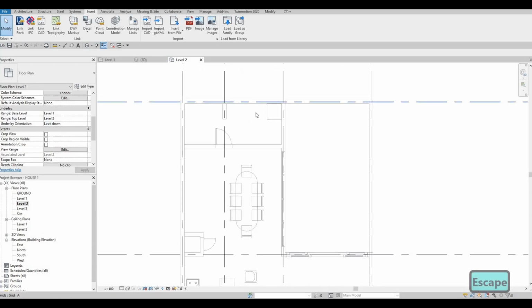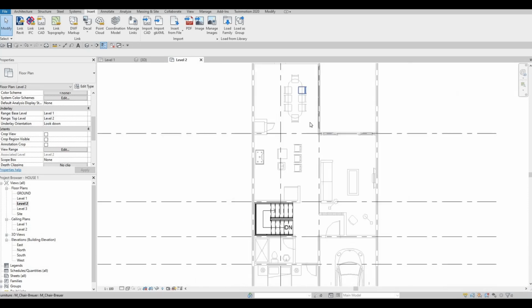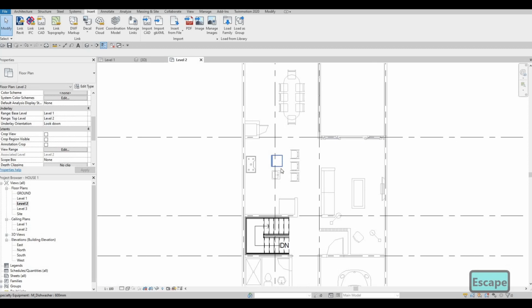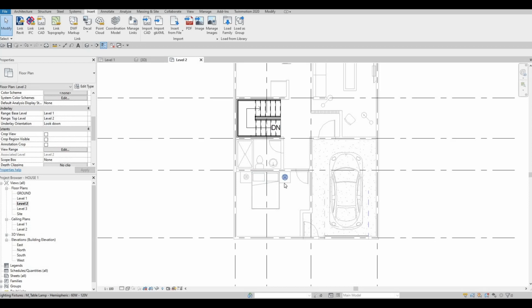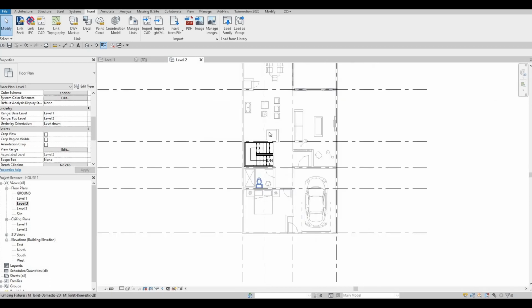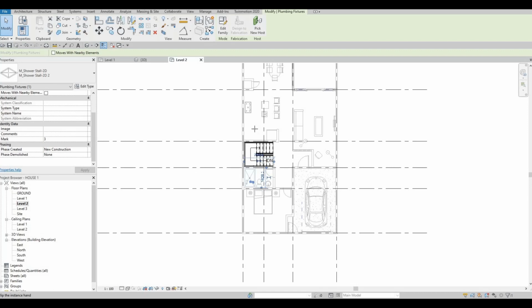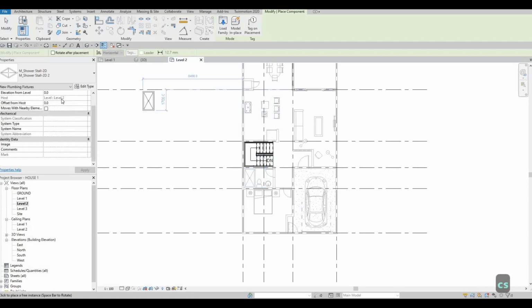And if you notice, you'll be able to select them. If not, you need to uncheck one of this. So the underlay, select underlay. Because if this is X, you won't be able to select ones below. So you will need to uncheck this, and then you'll be able to select that. And it's better to do that as well because we already have the bed, for example, the nightstand and everything. We will be able to select that, CS, and then add it to level 2.